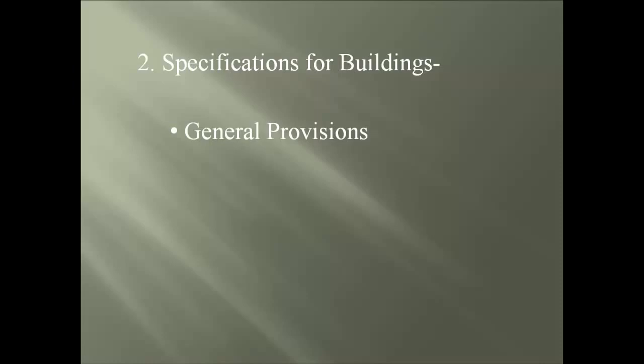Second comes a key definition, which is built up heavy shapes. That means any material thicker than 2 inches. The specification moves into drawings, being consistent with the Code of Standard Practices of Steel Buildings and Bridges. And the following points are provided: stability analysis and design, design of members for tension and compression, plus flexural, shear, and torsion, while lastly covering the design of composite members.